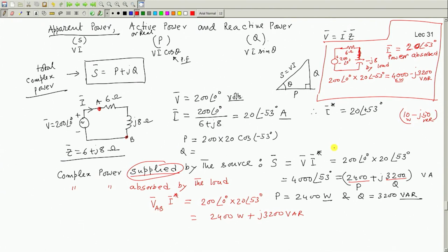The real part will always be positive. Therefore, a capacitor source can be considered to be generating reactive power. We could say the other way also, that inductive generates, it does not matter, but from this sign we will be able to know whether the circuit is capacitive or inductive, just looking at the sign of the reactive power.